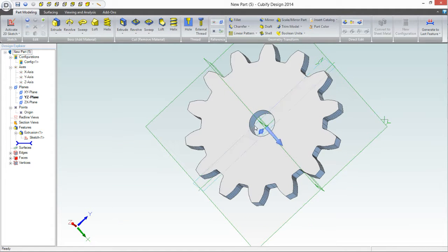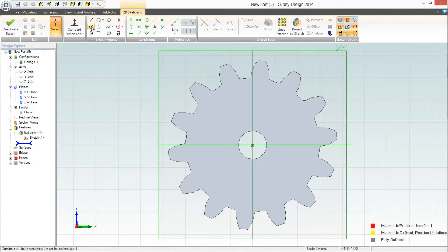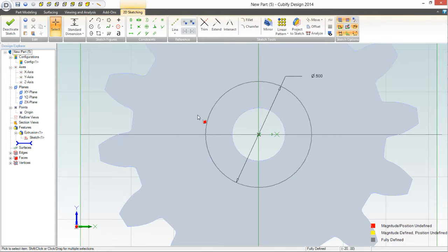If we want a locking hub in this, that's really not much of a problem either. We can create that locking hub right here in our 3D program. Go back to sketch and see, we can pick up a circle. We're in sketch mode, and we'll snap right to the middle of that. And we go out here, it says 0.556, but we can type in, I've let go of the mouse, and we can type in 0.5 and hit enter, and it'll give us an exactly 0.5 diameter little hub, or hub reinforcer right there in the gear.